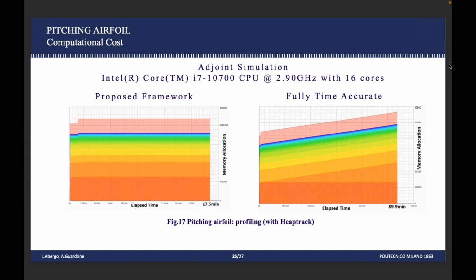I can send them to you. Yeah, and also the CFL has to be lower compared with a standard simulation. But once the harmonic balance converges, it converges really well. Either it does not converge or it converges really well and really quickly. There is nothing in the middle that I can see. Okay, thank you.